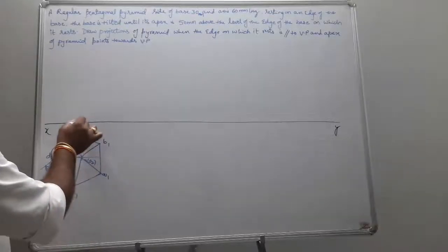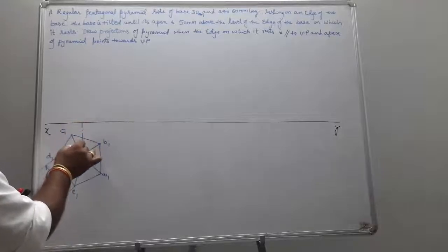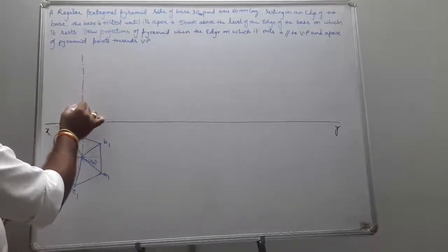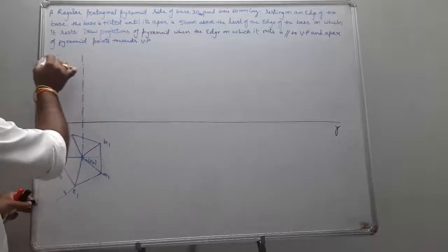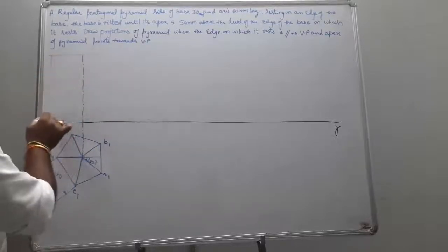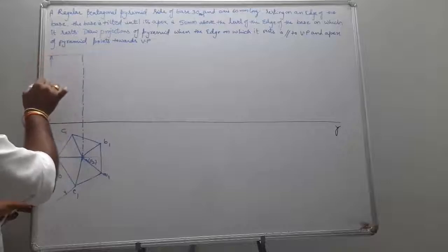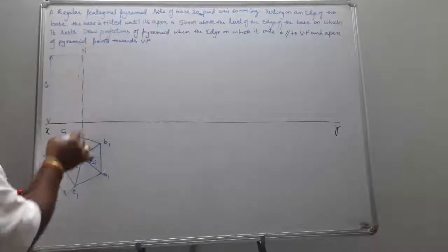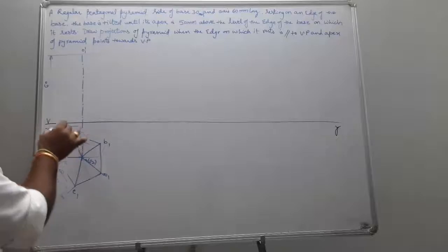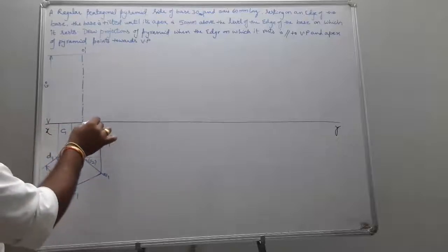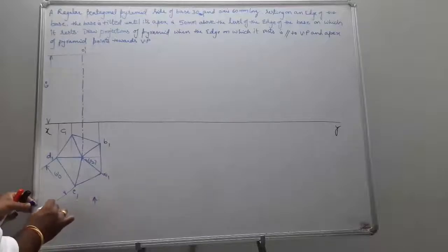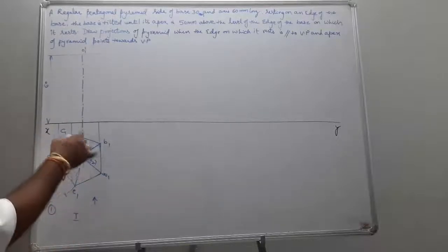Okay, and this was your axis. Given axis height is 60. Given it is 60, so this becomes your O1 dash, and draw the vertical projectors from the front view. This was the front view. Step 1, stage 1. And tell me what are the points which are coming on the base.